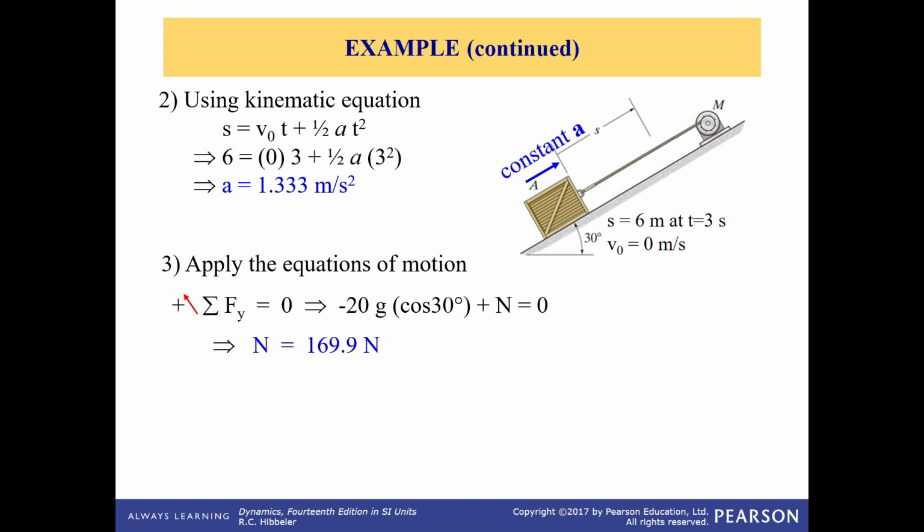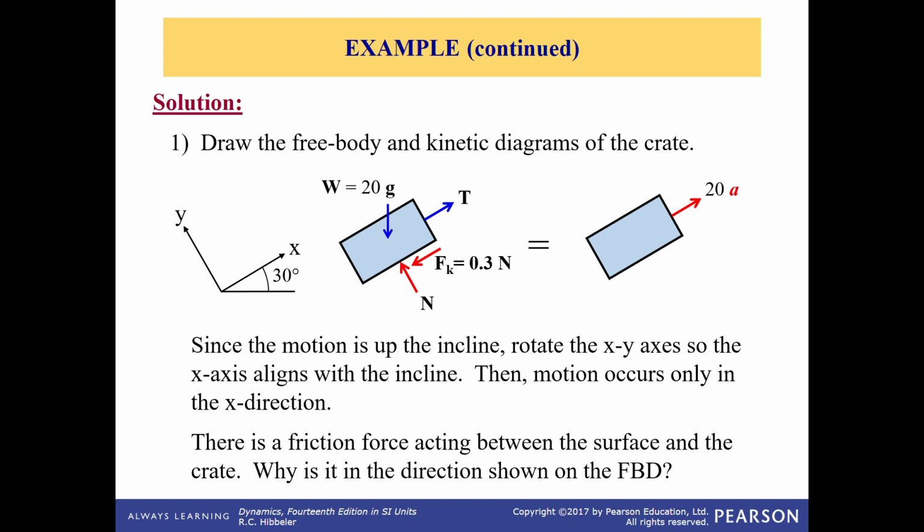Okay, this is actually referring back to the free body diagram. Let's take a look at this free body diagram. If you see the y direction here, which parameter do we have there? Obviously, N is moving towards this direction, while the weight itself is in vector form. Since we have two directions, we need to convert the weight force into two components, Wy and Wx.